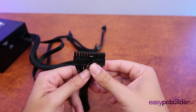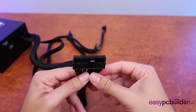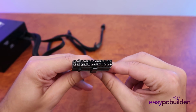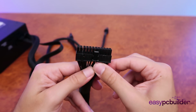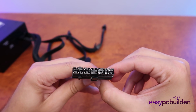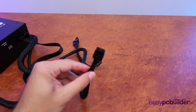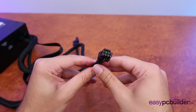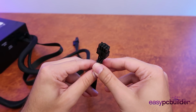So from the power supply, there's three key power connectors that would be required for any gaming computer. First is your primary motherboard connector. This is a 24-pin connector that connects to your motherboard and provides power to most items connected to your motherboard. The second here is your CPU power connector. Now, this is an 8-pin power connector that provides power directly from the power supply itself to your CPU.